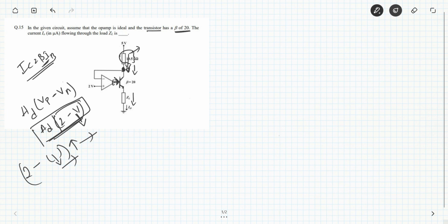So in this scenario, the operation of negative feedback is not coming into play. That is, when the output increases, the feedback loop should stabilize and decrease the input. But here, when the output increases, the feedback loop increases the output much more, driving the op amp into the saturation voltage.